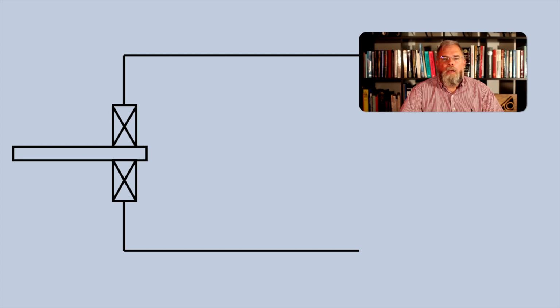An alternative approach to burner staging, which was adopted by Siemens for their silo combustors, is fuel staging within a single burner. This approach might be combined with burner staging also, but typically this approach requires fewer burners. Often this is done by splitting the swirler into 2 or more sections, which are each supplied with their own fuel feed or stage. If we consider a typical 2-stage system, one fuel stage is close to the axis of the burner, which is often called the pilot stage, and the other is radially further away from the axis.